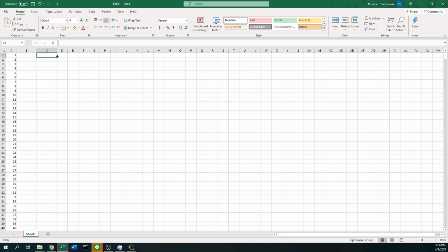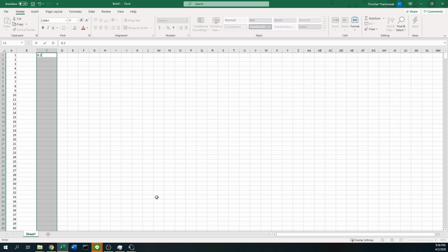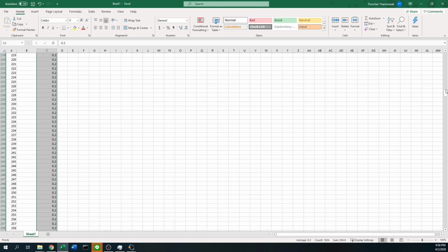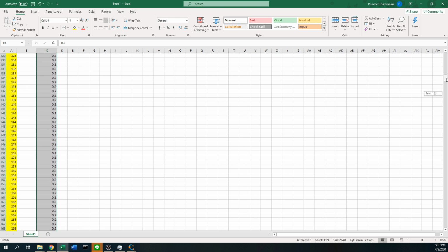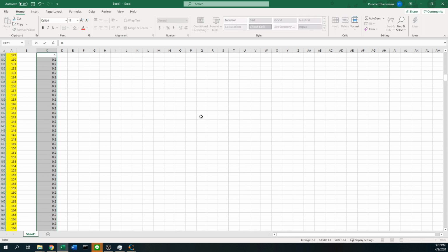Poisson ratio for... come down here, and I just put the 0.2 for concrete. I know that some cells there are steel, so I cover it up. Poisson ratio for steel is 0.3.